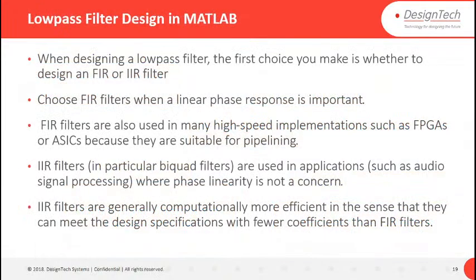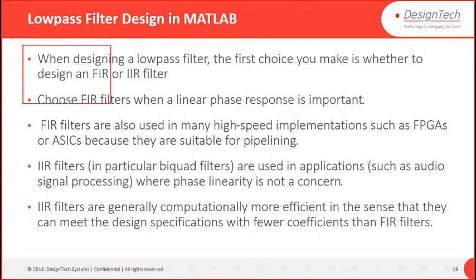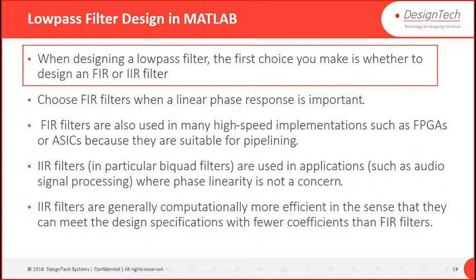Okay, low pass filter design in MATLAB. I am going to show you a low pass filter; in a similar way you can design a high pass filter. When designing a low pass filter, the first choice you make is whether to design an FIR or IIR filter. So you have to know the difference between them, and what kind of filter you are going to design. Okay.